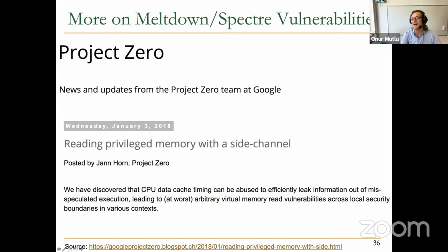Basically, people are trying to find a balance between the performance that you get out of speculative execution and the security holes or side channels that it creates. And later, research showed that it's not just speculative execution, but a lot of the choices that you make in the microarchitecture of a processor that is related to instruction execution and that affects the timing of different instructions in a data-dependent manner can significantly lead to side channels. So anytime an instruction can take different times based on a data value, and you can measure it, you can potentially create a side channel.